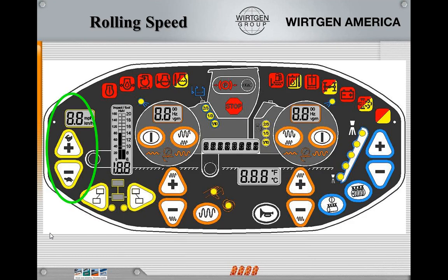And how we do that is basically, if we can control our forward and reverse speed and be consistent, we should have consistent impact spacing. If we have the operator controlling it manually, sometimes we're going 3 miles per hour, then maybe 2.5, we're going to get what's called an accordion effect in the impact spacing. Sometimes you're at 10, sometimes you're at 14, then maybe down to 9. Well, that inconsistency is going to change your ability to compact that material and get consistent density. If we stay at a constant speed, we have a better chance of having consistent impact spacing, therefore having more consistent density throughout the mat.